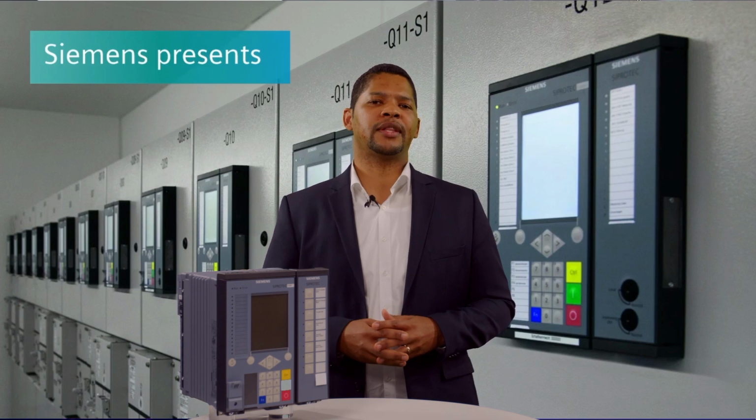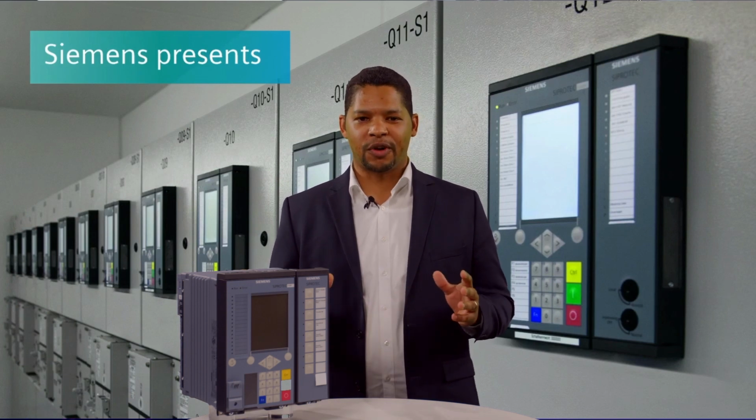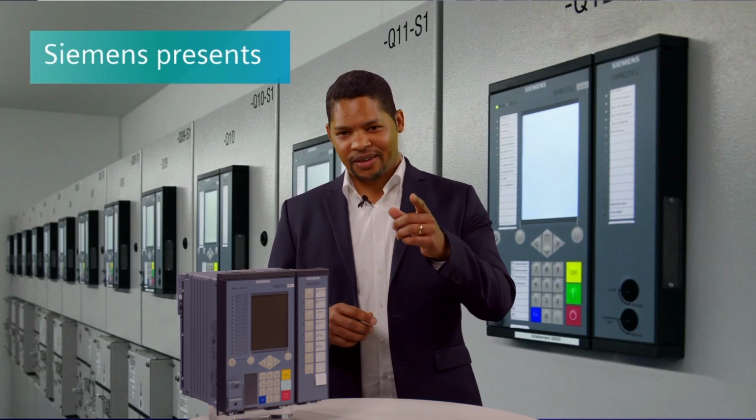And that's the first video. Our next video is about inconsistency warnings in the hardware and protocols editor. The video demonstrates the handling of the most common inconsistency warnings in the hardware editor of DIGSI 5. One example is the inconsistency warning right from the beginning if you add a SIPROTEC device with a line differential function. Here you go.